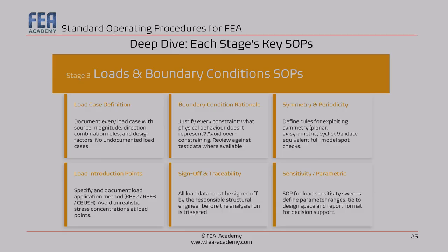So the load sign-off is a non-negotiable gate. All the load data, the magnitudes, the directions, the application points, the combination rules, because we combine some effects, must be signed off by the responsible structural engineer before any analysis run is submitted, and not after, not informally: a written record with a date and a signature.